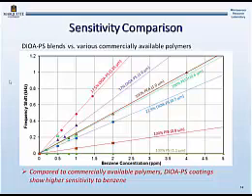And PEC is polyepichlorohydrin, that's relatively stable and sensitive. And PIB is polyisobutylene, so that's not very sensitive, but it is stable. That essentially leaves us with 1 good commercially available polymer, that's PEC. So you can see that the plasticizer polymer coatings gave us in part much higher sensitivities. And even this one is still relatively good.